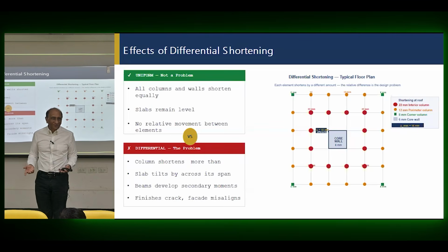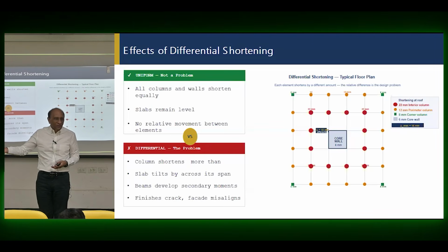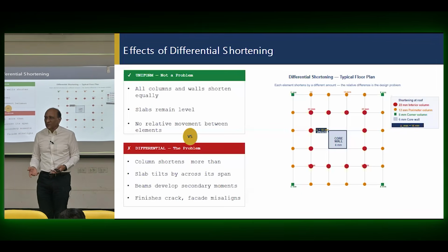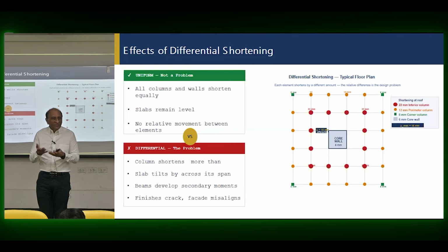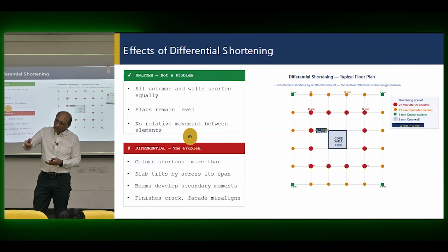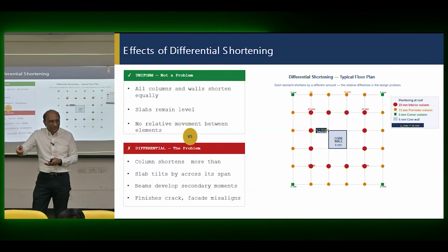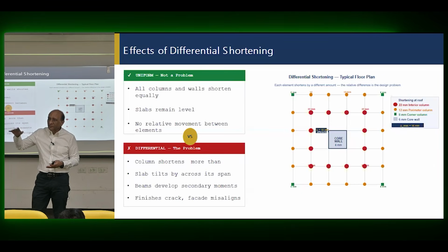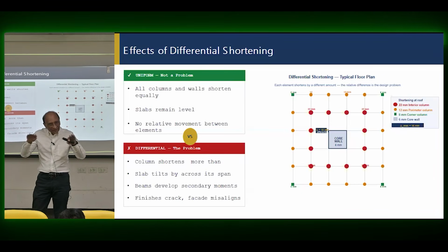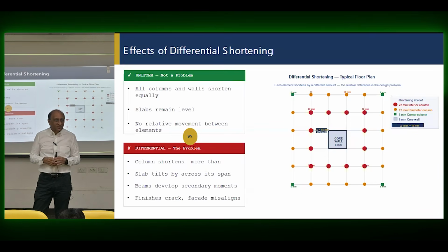So how do you handle that problem? You have to make the floor unflat today, so it will be flat tomorrow. But then the unflat floor exists today, which is also not good. So somewhere a compromise has to be made with these acceptable limits. Okay, the total acceptable limit of the floor is 3 millimeter. So I will make it 5 millimeter up, so it will go down by 3 millimeter, something like that. So you play around with the tolerances and play around with the calculations to get something that will be more or less acceptable during the life of the structure, at least 10 years.